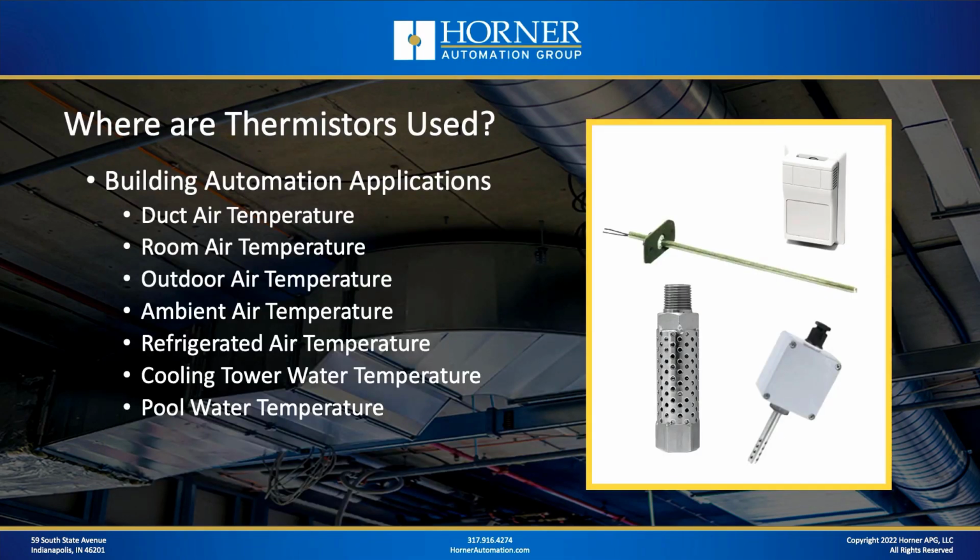Okay, now more specifically, where are thermistors used? Of course, we've talked building automation, we've talked HVAC, but what we can be talking about are the different temperatures that need to be measured in those particular applications. So you could be talking about the temperature in an air duct, the temperature of a room, outdoor air temperature, just ambient air temperature in general, let's say in a warehouse. It could be air temperature in a refrigerator, for instance. And it's not always air. It could also be water temperature of a cooling tower or maybe a swimming pool, whether it's a public pool or something of that nature. So again, you can see these most common applications are certainly building automation and HVAC type related.